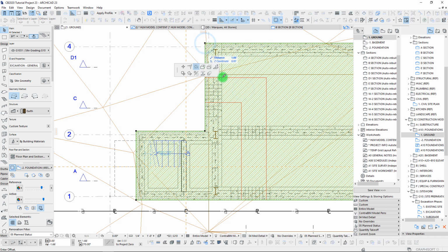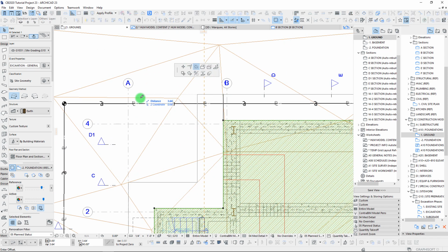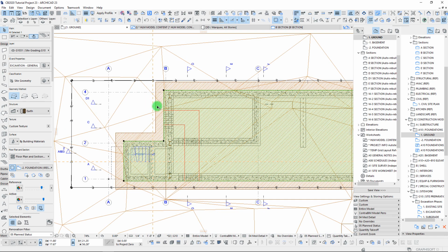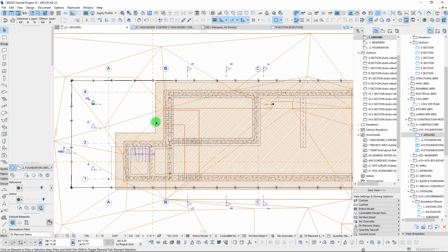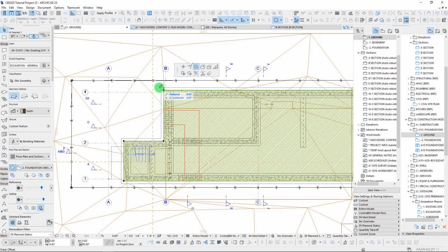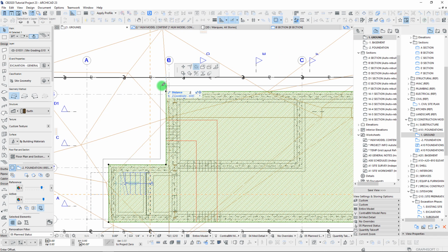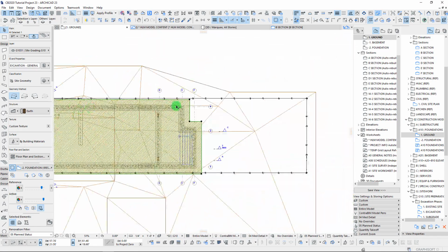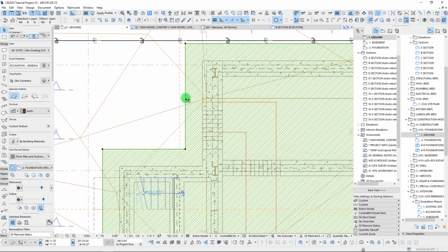We also need to actually offset this out. And in this case, we'll just take it about 2 feet for now. Some of these we are going to be pushing out further, and I offset a copy there. I didn't want to do that. We're taking our entire mesh here, and we're just offsetting 2 feet. So that puts us pretty much right on our property line over on this side. And then in some of these areas, we will certainly be pushing these out. So, but nonetheless, we still need to get our sloping down to our footings again.